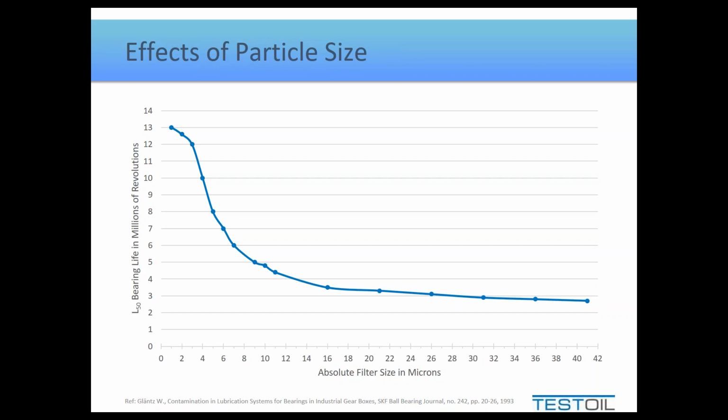And if I can't say that something's practical, feasible, and economical, I'm probably not going to recommend going ahead with it. So when I look at this study, where I like to draw your attention to is somewhere around the 5 micron filtration. At 5 micron filtration, we can probably get that done practically. It's usually quite feasible, and the economics work out much better then. So that would be about a 3 times life extension. Worst case scenario, a 2 times life extension. Point being, yes, we can see where that curve meets reality. Where the curve starts to get very theoretical is in the far, far left.